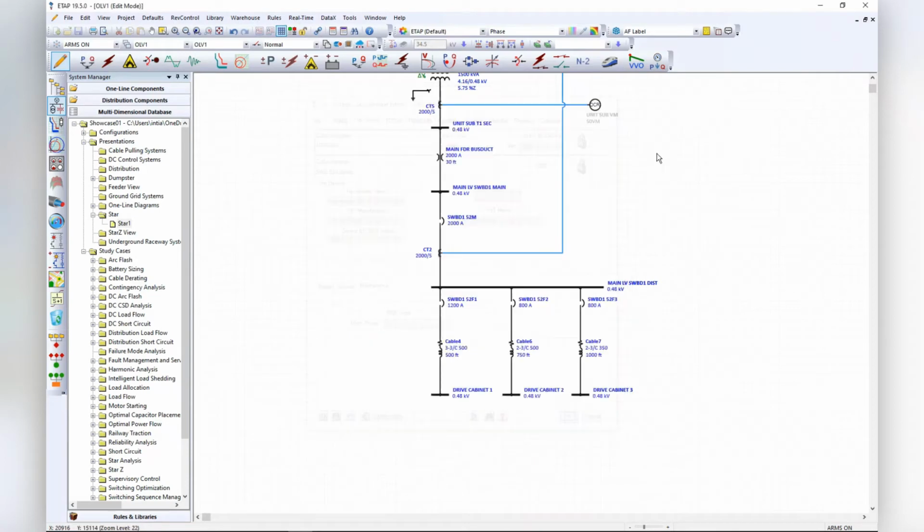The problem with it, of course, and you're not gonna see it in here because we don't have any across the line motor loads, is that it's gonna miscoordinate with everything downstream of it. And maybe that's not a problem. Maybe everything you have on this switchboard is simply part of the same machine. And if you lose drive cabinet 1, you don't have a reason to have drive cabinet 2 and drive cabinet 3 going on. So it's just a matter of, well, if I need to trip, let's just trip the whole thing. I don't care if it's miscoordinated, but that's not always the case.